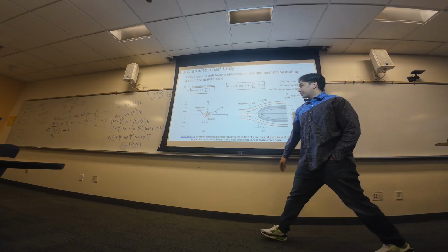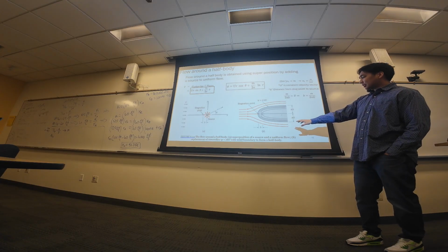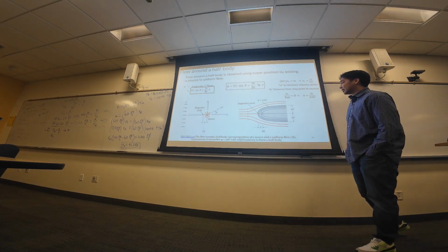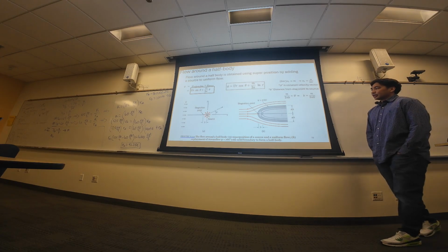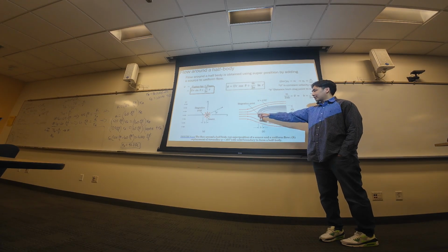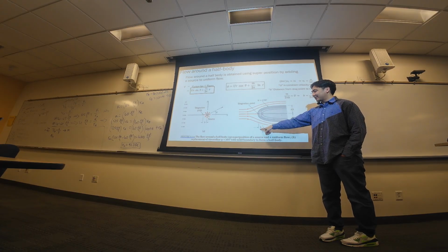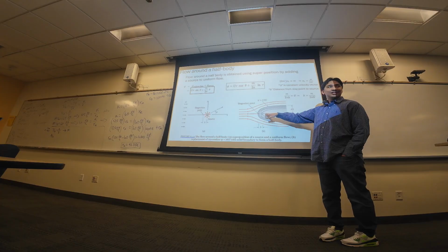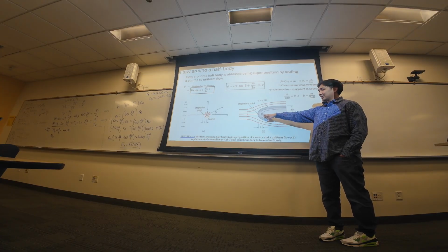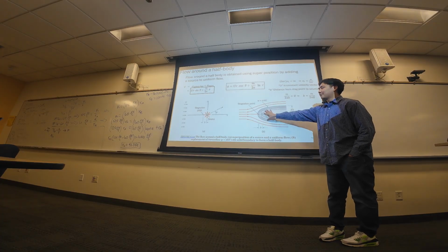We already went through this diagram. Here is the half body, right? So here is the stagnation point. And the stagnation point, as we read in the previous lecture and example problems, is just when your velocity equals 0. So at this very front part is where your velocity equals 0. This little circle here explains the distance b. It was annoying because they didn't explain this in the textbook. This is just your source. And I think that's what the empty circle symbolizes. It's the flow coming out of there for this half body.